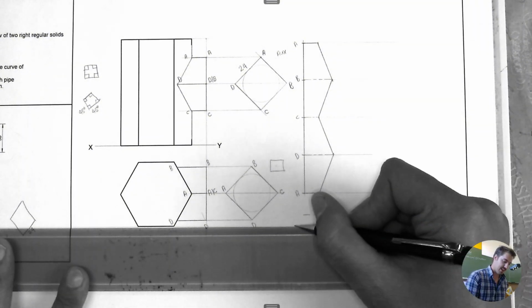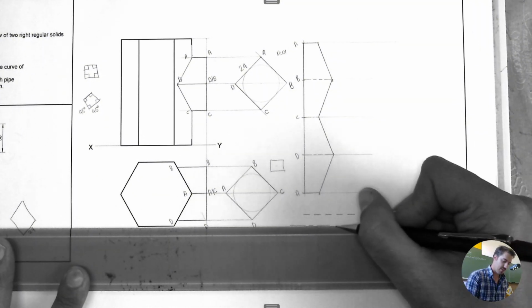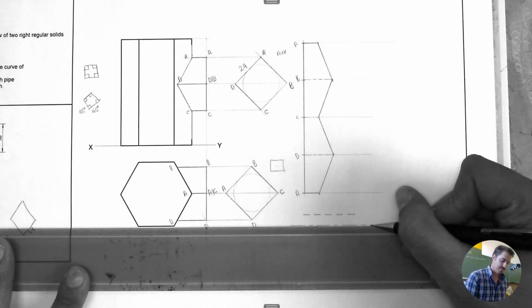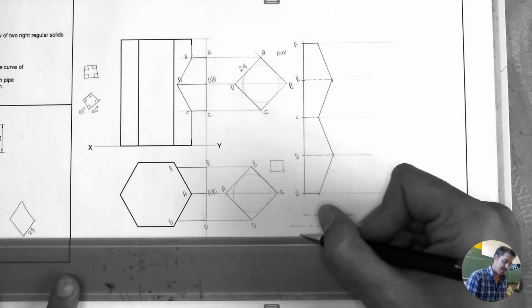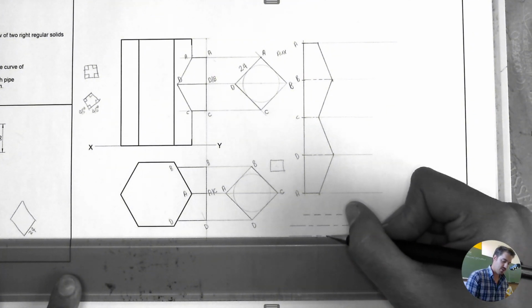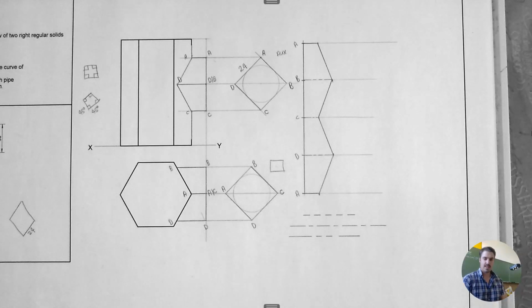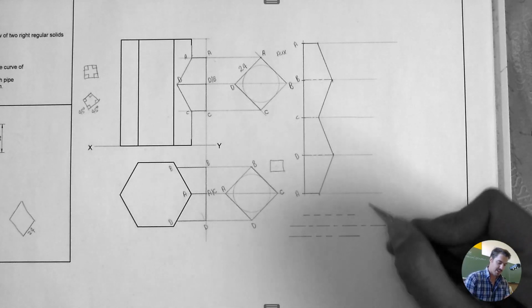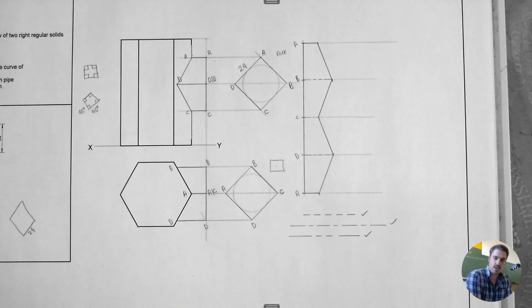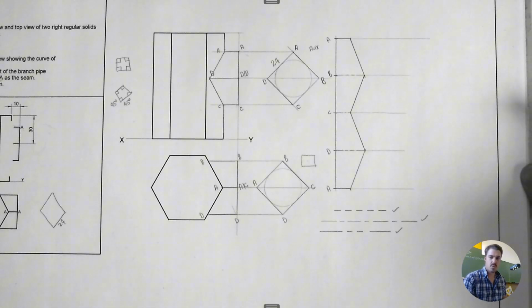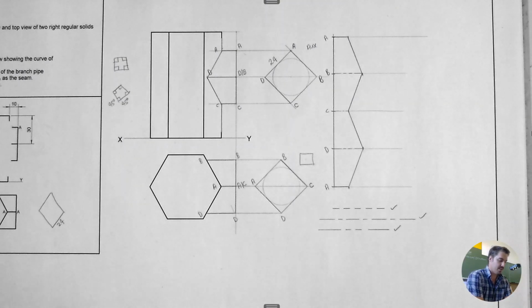Then you have a center line, that's also called a chained line, that looks like this. And then we have folding lines. That's a long line, two short lines, and a long line that looks like that. So please, you need to know hidden detail, center, and folding lines. They are different. So this is what your development is going to entail. This is from start to finish what you should know.